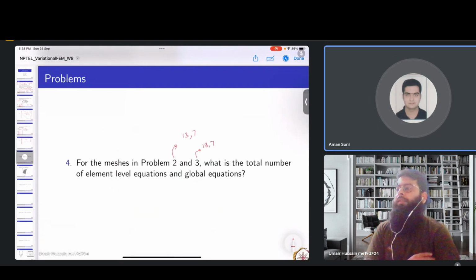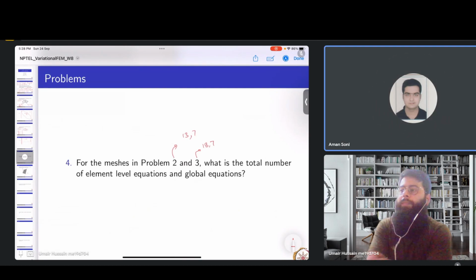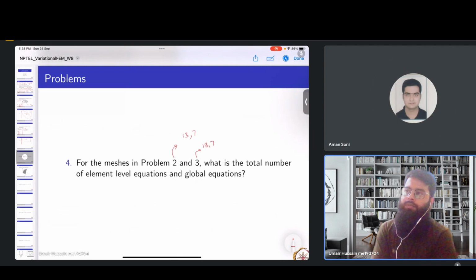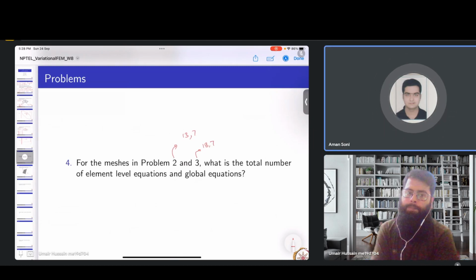That's why in general, when we have more complex BIW parts and go for a tet mesh, industries use second order elements. But when they want to reduce the computational cost, they hire engineers who are able to do shell meshing for that also.